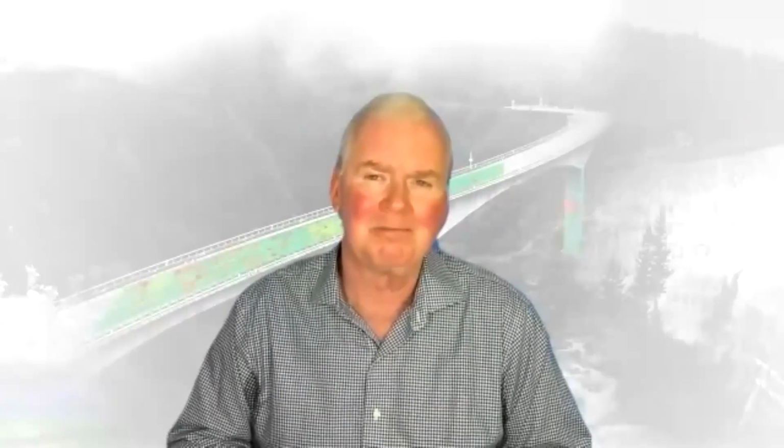The impact echo is primarily going to work for finding the absence of grout and not telling you the corrosion or the condition of tendons. Certainly, if you can evacuate people and you have access to both sides, you can do detailed X-ray radiography of tendons and image wire breaks if they've separated. That's a tomographic approach that can also be used, but it has the limit of keeping people away from it because of the high radioactivity associated with the radiography.